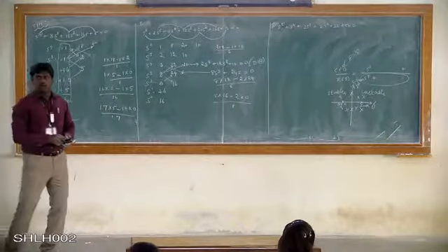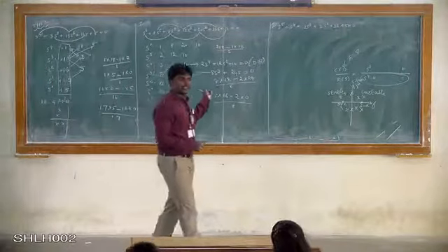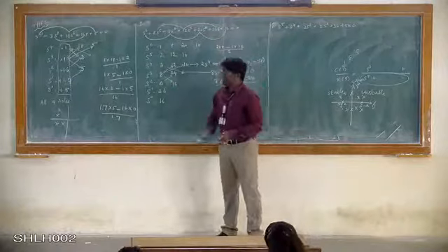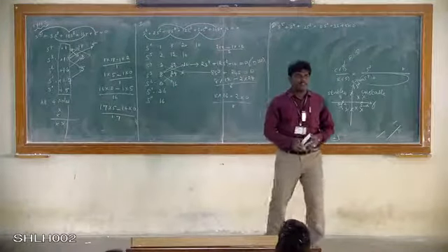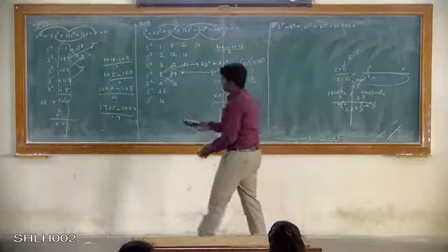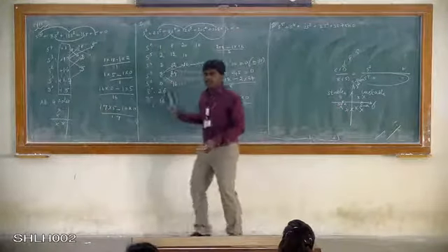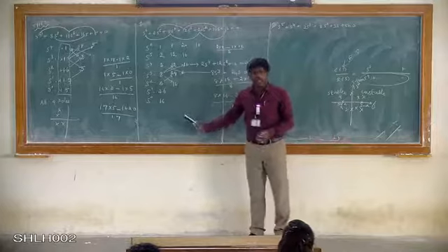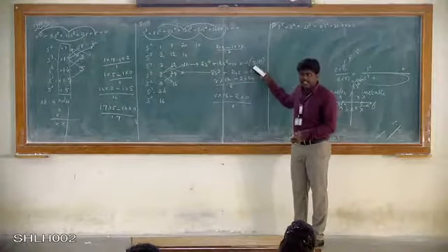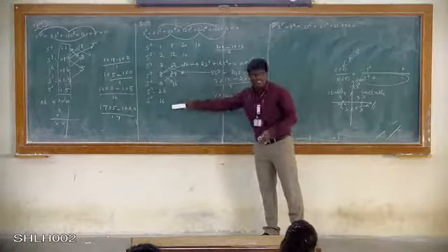Right? So in this particular problem also we have made the Routh table. Okay. So if you are looking at this particular column, and all these are positive, then you would say the system is stable. But in this problem, we will not be able to say that here, because we have differentiated this equation and we have got this table.